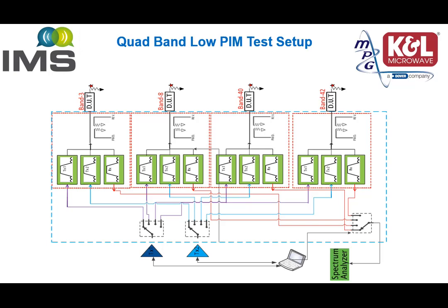This low-cost solution is based on the idea that high-ticket components such as amplifiers, signal generators, and spectrum analyzers are found in every lab. In our approach, the fixed filtering solutions are connected together via switch matrices and couplers. In this way, we can maintain a very good dynamic range and a low-cost solution.